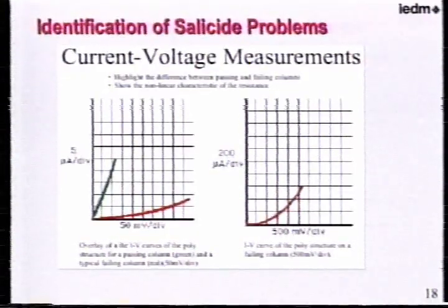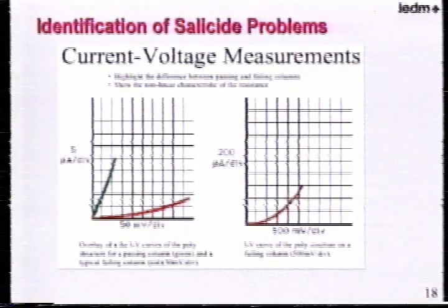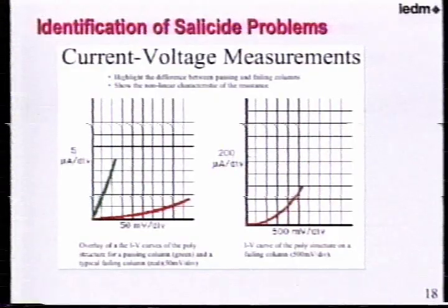You may not be able to do this in an SRAM because SRAM, the situation is tight. You have a tight layout, compact. However, you may be able to do it in a logic block where you have a long line with butted transitions. You may be able to widen it. So there are two ways to skin this cat. One is to fix the process. The other is to actually do something to the design itself. And we'll come back to this theme again and again.